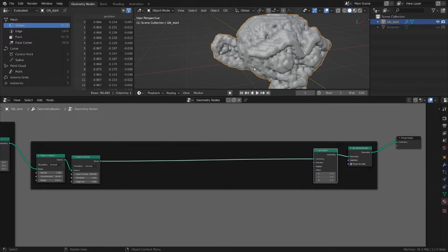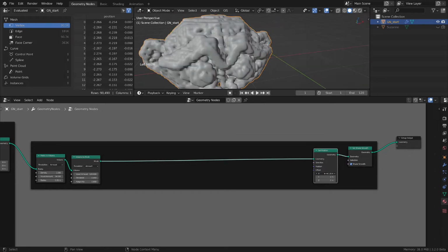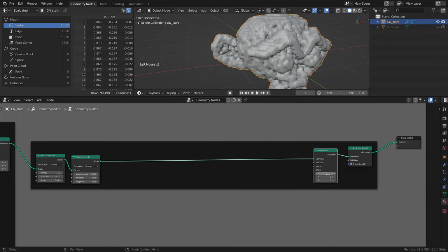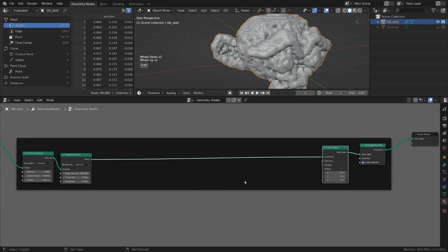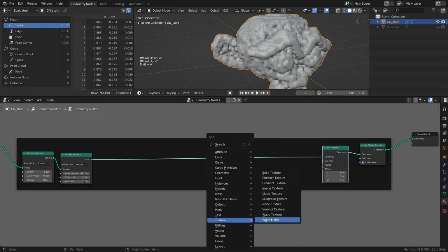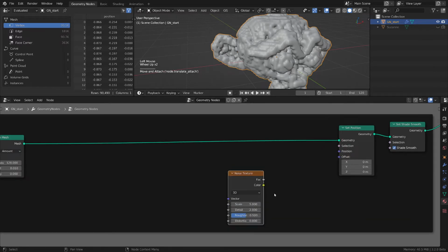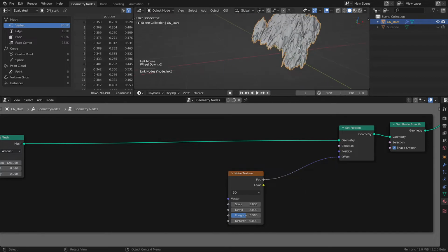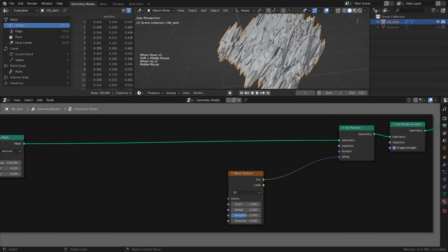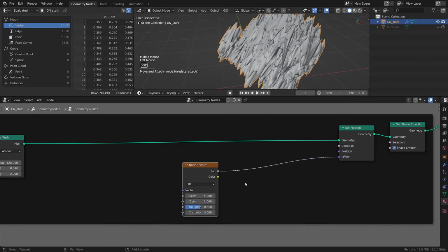And the way to do this is to distort this surface at the point level. So let's do a texture-based distortion. Take a noise texture and let's do an offset, something like this. And immediately you see this working. We have a few problems.